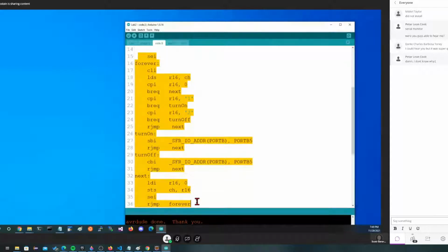Basically, it's kind of like resetting the whole thing so that we can receive the next interrupt or just sit there. That's exactly right. If we didn't do that, we would just keep receiving the same character over and over again. In this case, it wouldn't matter. We would just keep the light turned on. But what if it were incrementing something? If we were incrementing a value, every time you saw that number, it would increment. And it's not a new character. It's the old one. We've already processed it. So your assessment is exactly right.